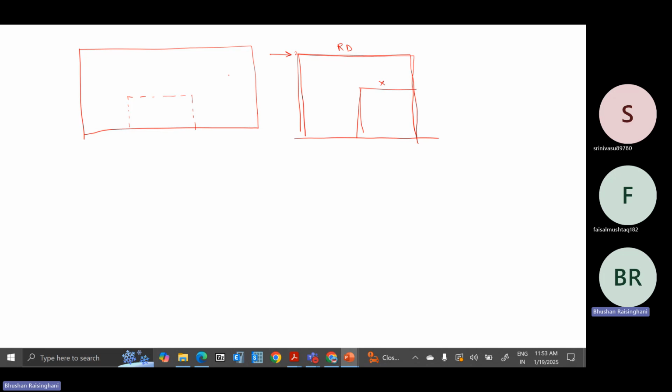And in some cases, when the aspect ratio is not mentioned, so L by B less than 3. If L by B is greater than 3, then maybe it is a flexible diaphragm. So aspect ratio is just tentative. You have to apply your understanding and ascertain the flexibility. Then you have to take it as a flexible or semi-rigid diaphragm.